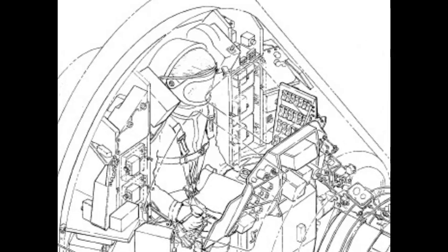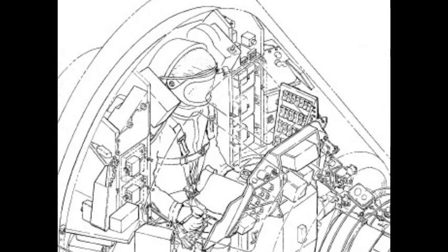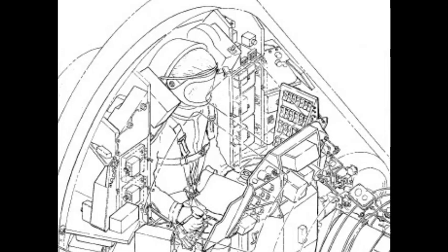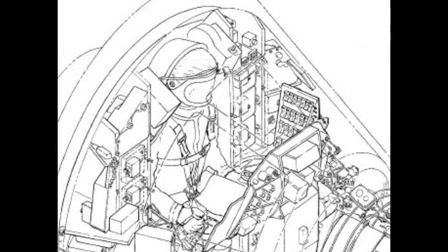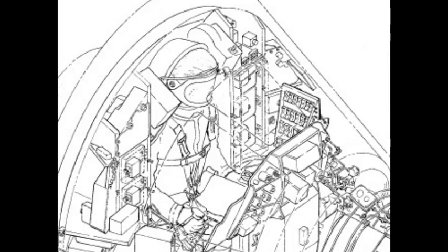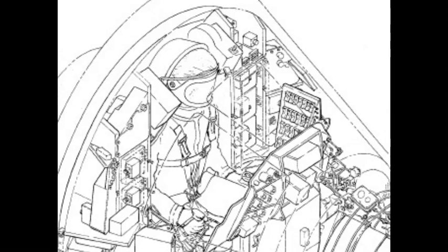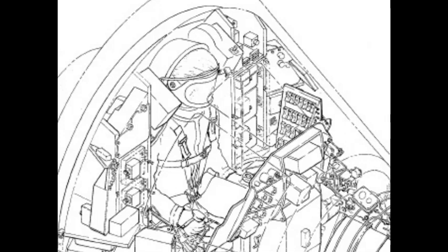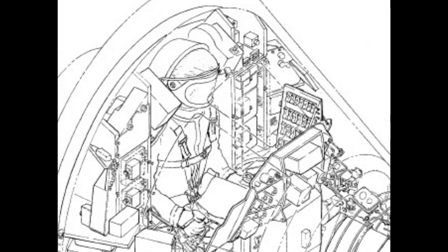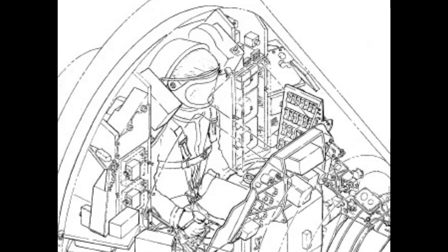The fairing is attached to the capsule by a mortar gun, located in the capsule recovery compartment, and 3 index pins in the antenna fairing lower mating flange that align with 3 holes in recovery compartment mating flange. 2.12. A spring-loaded destabilizer flap is attached to the top of antenna fairing opposite the pitch horizon scanner. The destabilizer flap ensures capsule correct re-entry attitude during capsule abort and re-entry phases.